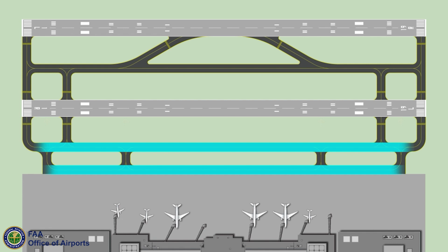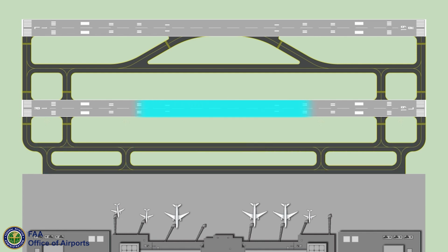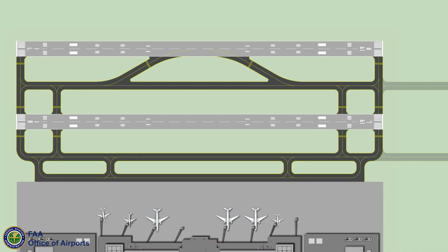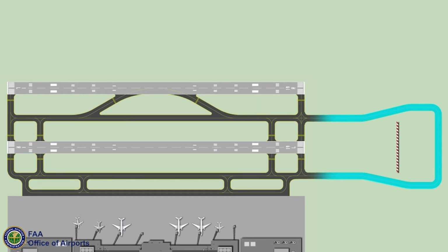Providing dual parallel taxiways at busier airports to enhance airfield capacity and departure queuing, minimizing or avoiding cross taxiways crossing a runway in the middle third where aircraft speeds on the runway are greatest, providing cross taxiways in the outer thirds of the runway where aircraft speeds are lower, and providing end-around taxiways or EATs at busy airports to reduce frequency of runway crossings, thus reducing runway incursion risk.